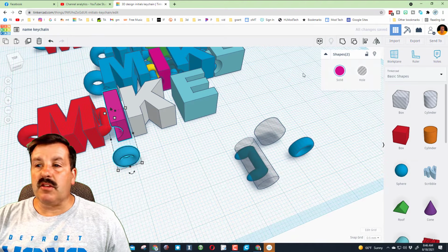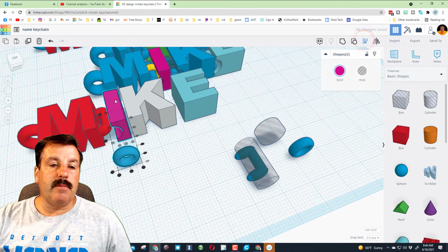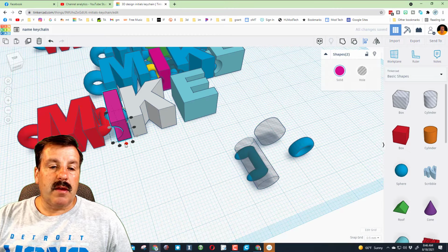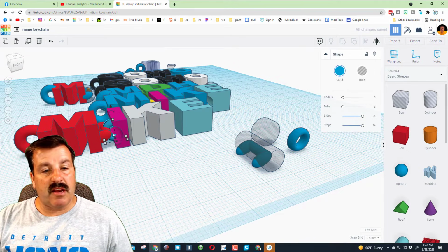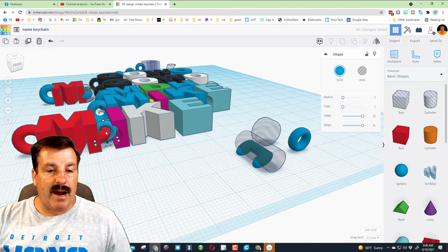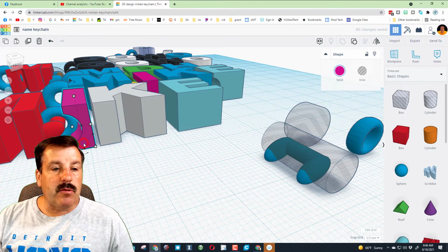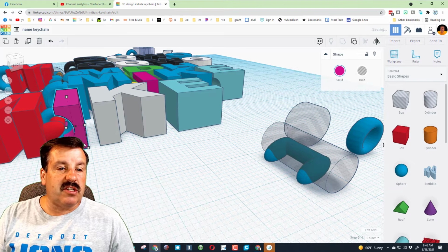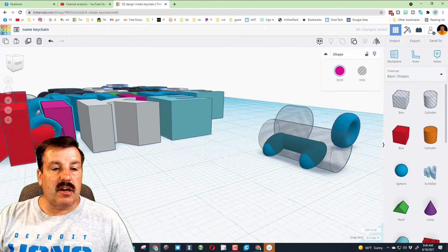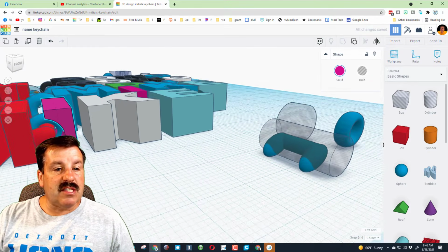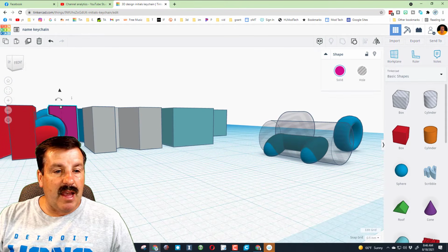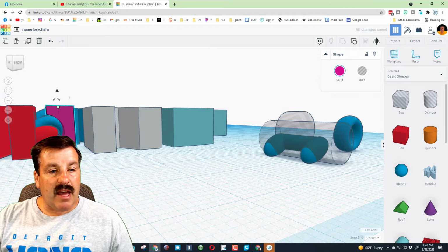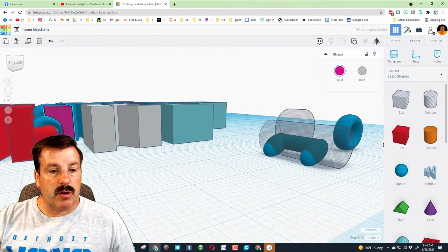Once again, select the 2, click align, make that pink one the master, and we want to go center. And you can click center, but then what you're going to do is nudge it with the arrow keys until it goes around that pin. Now you can click on your eye and you can nudge it in so it's going to connect just the way you want. So you can see there are gaps all the way around that, so when it's done it will be able to move. I think I can go one more click, which I think looks pretty cool.